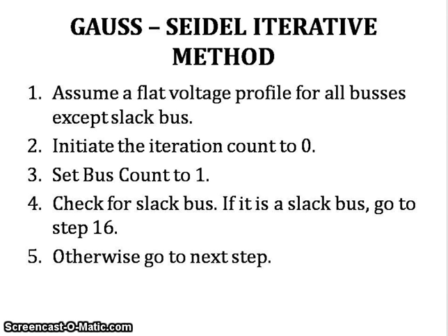As we know, all power load flow problems are to calculate magnitude and phase angle of the load bus voltages, reactive power at the generator buses, and real and reactive power flow in the transmission lines.